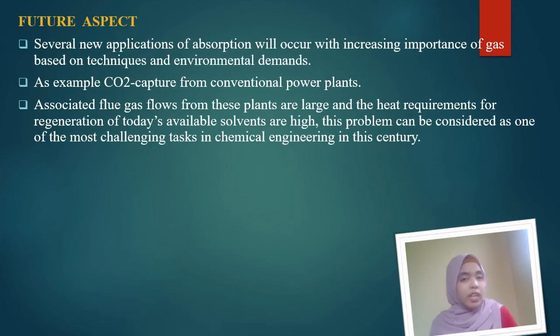For the future aspect, several new applications of absorption will occur with the increasing importance of gas-based techniques and environmental demands. As an example, CO2 capture from conventional power plants. Since these power plants contribute to the global anthropogenic CO2 emission to a very large extent, the associated flue gas from these plants is large and the heat requirement for regeneration of today's available solvents is very high. This problem can be considered as one of the most challenging tasks in chemical engineering in this century. Due to the low available partial pressure of CO2, chemical absorption has to be favored for this task.